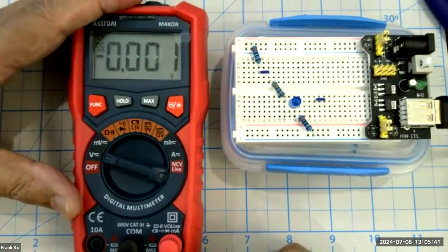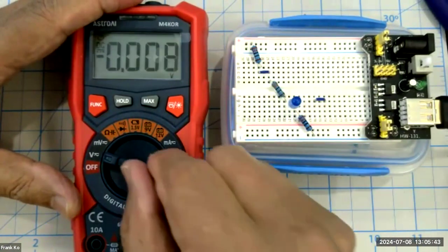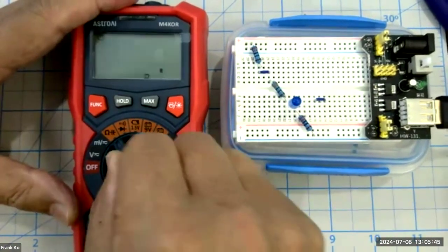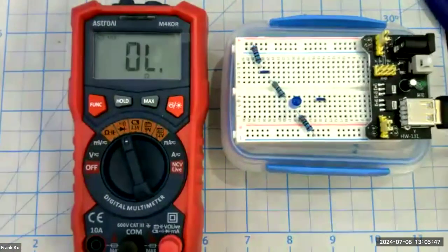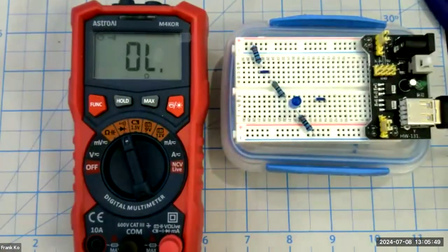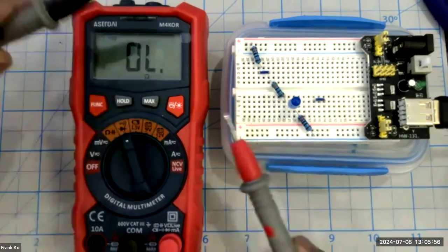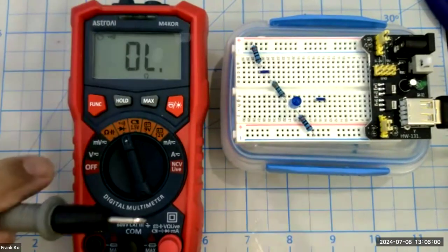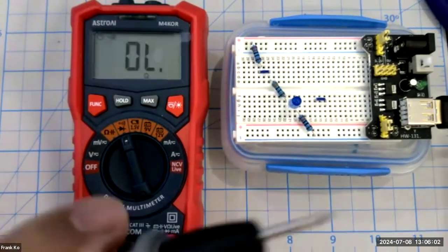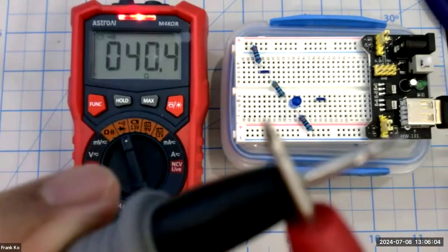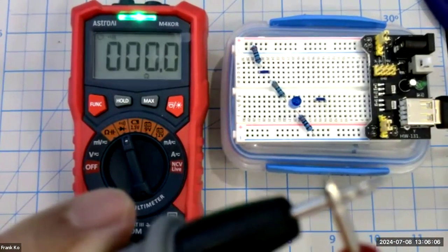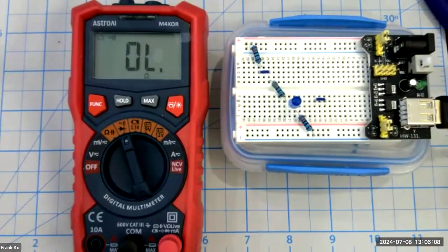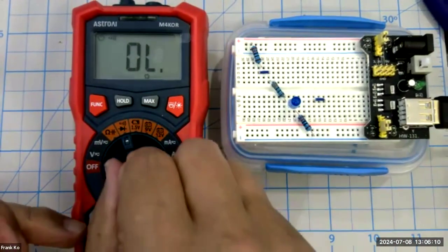First thing we wanted to do was measure resistance, which we did earlier. Well, actually, let's go ahead and confirm. So when we go to start our measurements, you want to do the continuity test. When we touch these two leads together, this should go to 0, and I should on this meter see a green light light up, and you may or may not hear the beeping tone through the microphone of the camera, but it beeped. So first thing you do is that.